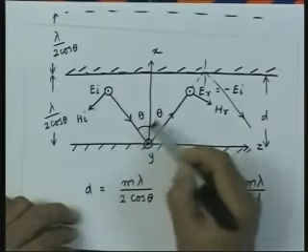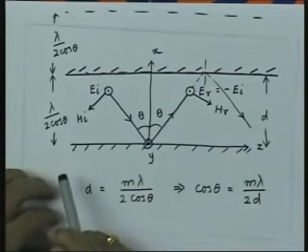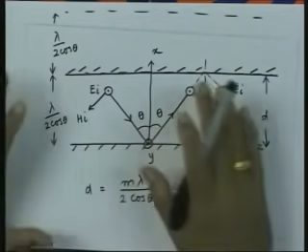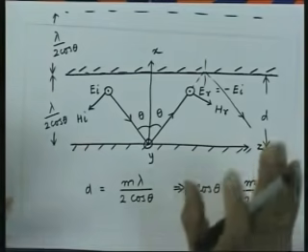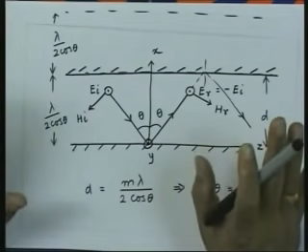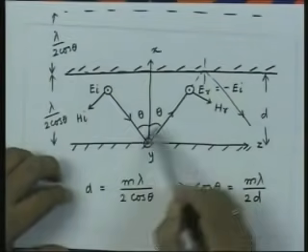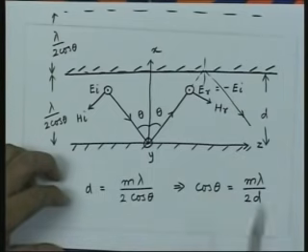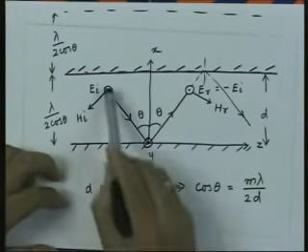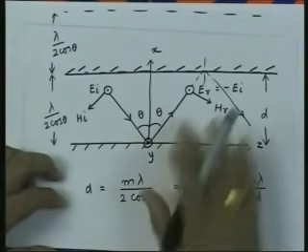However, now what we are saying is, if we make this structure bound in this direction, then I cannot launch an electromagnetic wave at an arbitrary angle of incidence. If I do that, this structure is going to reject that wave, it is not going to accept that wave. If the wave is launched at these angles which satisfy this condition, which are discrete now, then and then only you can have a sustained propagation of electromagnetic wave.